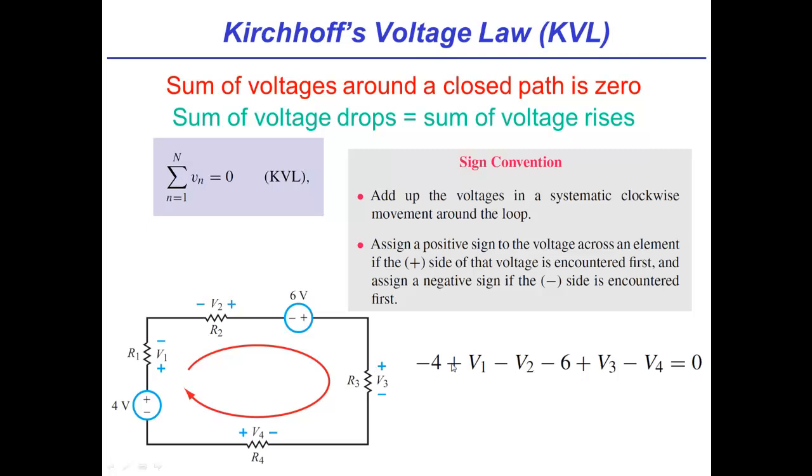And in fact, it turns out I almost always do it clockwise, just so that I don't make mistakes. Yep, I do it clockwise too. So that's why we picked to do this one clockwise. And what you do is you just add up the voltages as you go in a clockwise direction. Now, it turns out adding up voltage is pretty straightforward for resistors because you'll just define where you go in as positive and where you come out as negative.